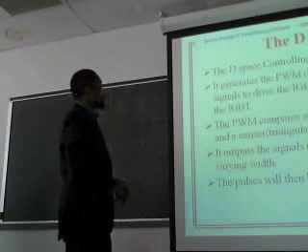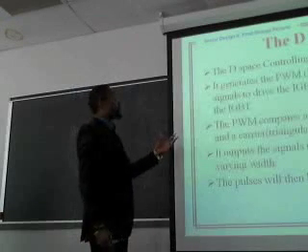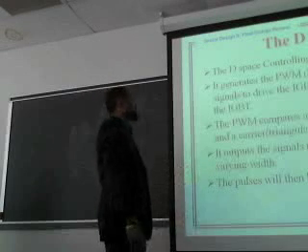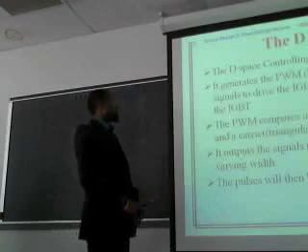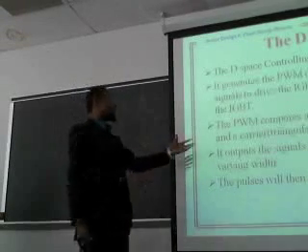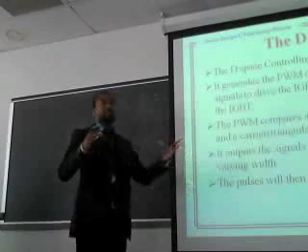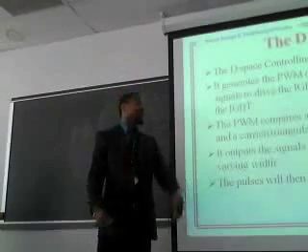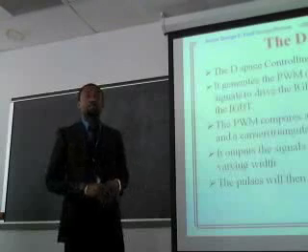And it generates the pulse width modulation signal to drive the gate driver and control the IGBT. The pulse width modulation compares the frequency signal, that's sinusoidal, and the carrier frequency triangle. I'm going to show that in the picture because it shows what it does basically. I'll show that in the next slide so you have a better picture of what I'm talking about.